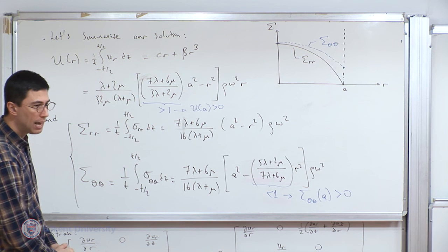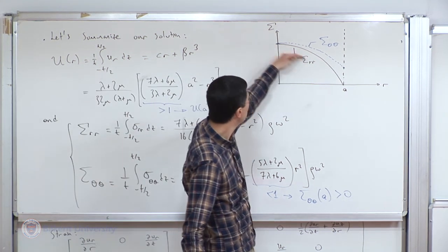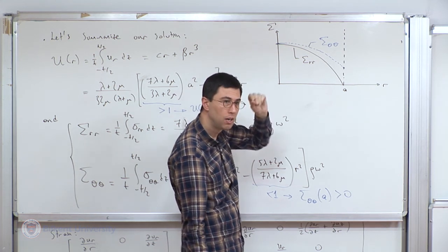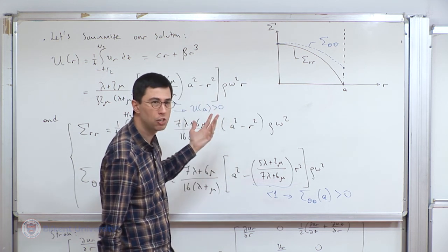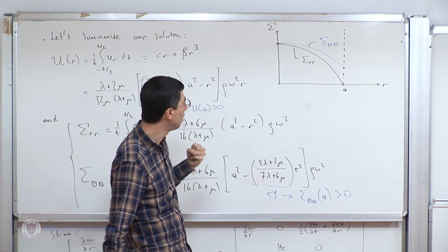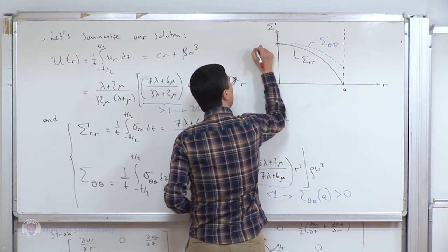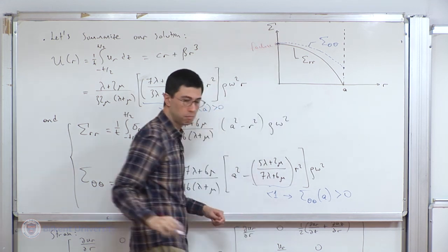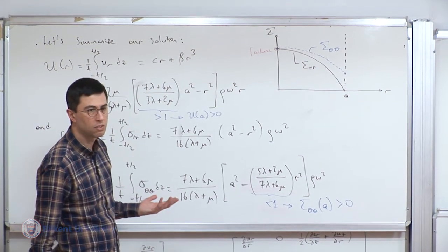And now when you look at that solution, what you see, as we already discussed, is that the stresses are a maximum right at the center. So if you were to worry about whether your thin disk, whatever application you have, is going to fail or not, the point you should be concerned with is this point. Probably, okay? In particular, if it's brittle, let's say.